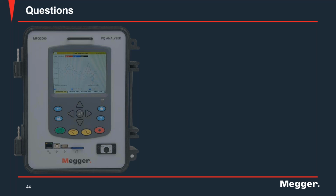So the recommended way would be to analyze the data in MPQ software, look at the different trigger levels, look at the parameters that are causing a certain PQ event, and once you analyze the data, you create a report, and that report can go into PowerDB in PDF format.